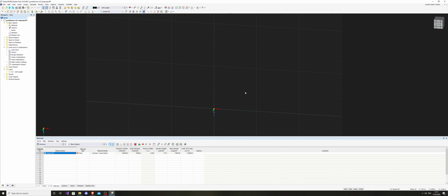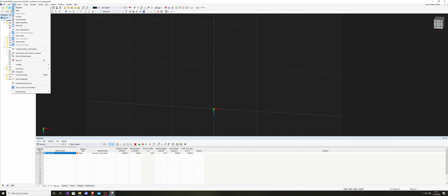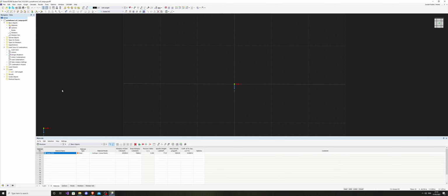Now for my preference, if you want to get perfectly 2D, go to View on the top left, and go down to Select View. Now I want to be facing the opposite direction, because the Y direction is coming straight at my face, so I want it to go the other way, in reverse Y direction. And there you go. It gets you into this view. And it's a lot better, a lot easier to work with.